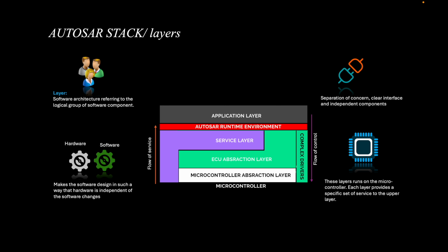and you will have a service layer. Here mostly you will be dealing with all the diagnostic related things, like if you want to trigger a DTC, or if you want to trigger something in the vehicle. All these things work with the diagnostic service, which is provided with the service interface.